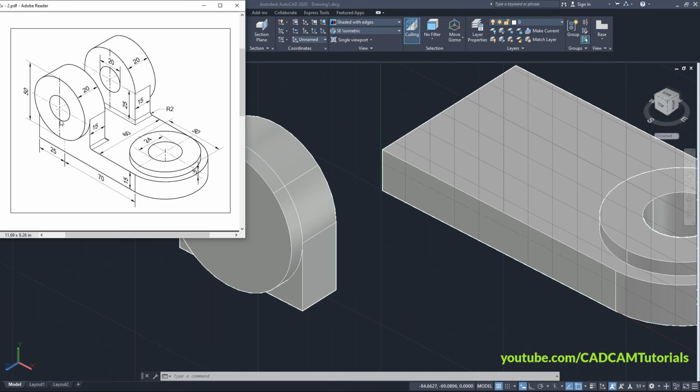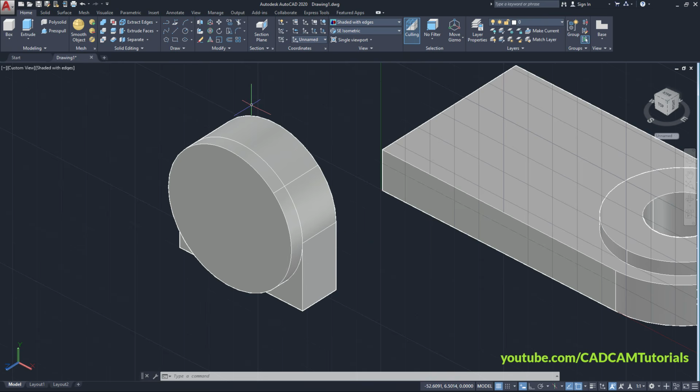Then there is this hole of 20 diameter. Again click on circle. Now here it is not showing center object snap. To show center object snap, take your cursor on the circle and click on center and specify radius of 10. Enter. Then again click on press pull. Take your cursor inside this circle and click. Take it outside and click. Press escape. Then I don't want these grids.